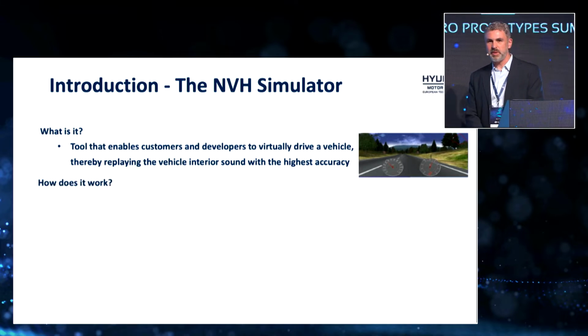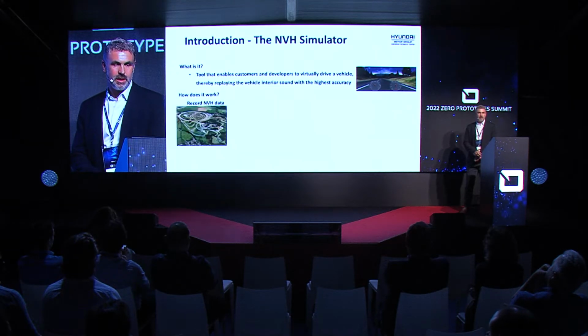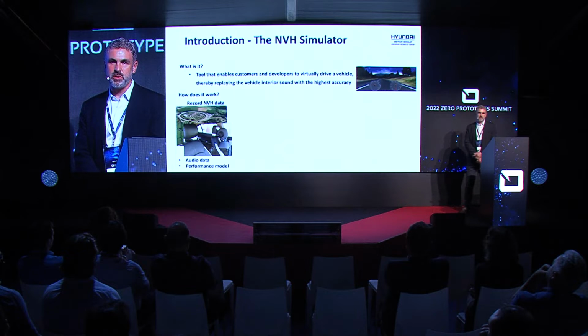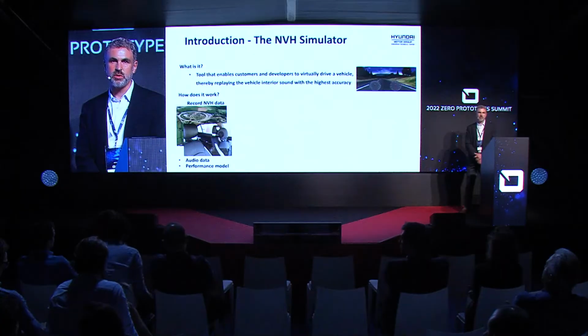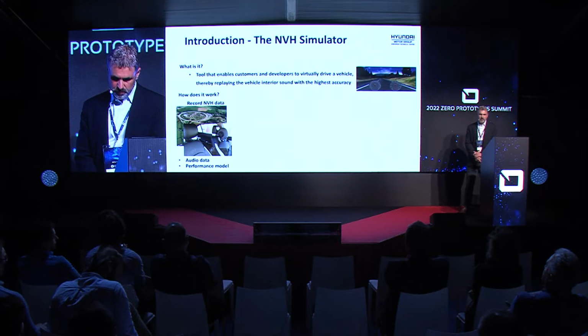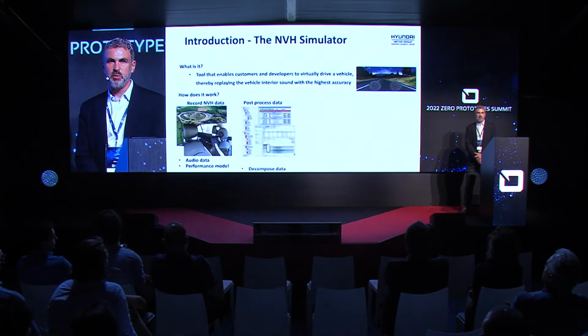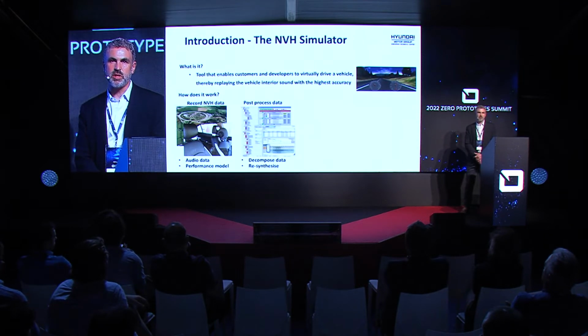So maybe a little bit different to some of the other applications of the simulator, of how it works. The first stage when we go to a simulator model from NVH is that we have to record some data. So we take a vehicle, we go to a proving ground, and we have to do many different measurements on different road surfaces and different driving conditions, measuring then acoustic responses, and also measuring the vehicle performance. Once we have the data set, we move on to the post-processing.